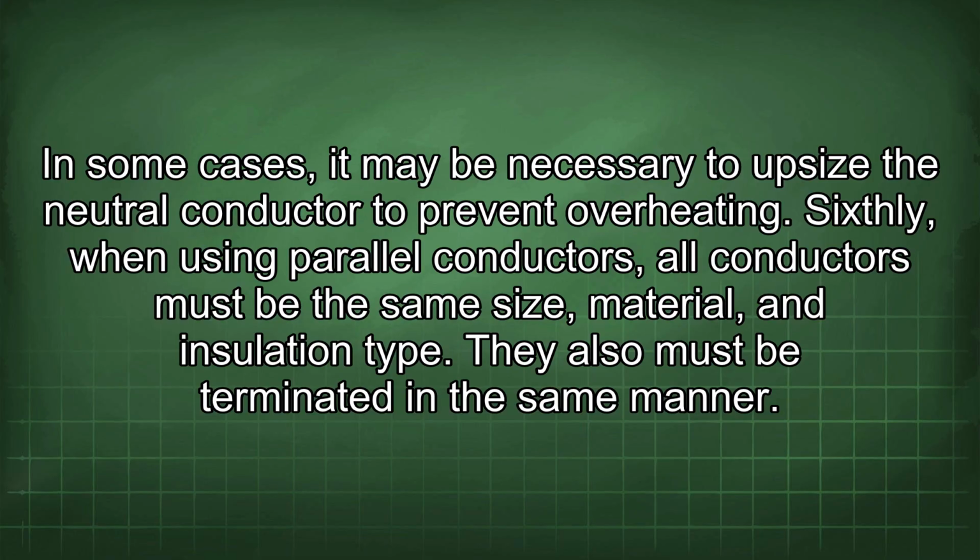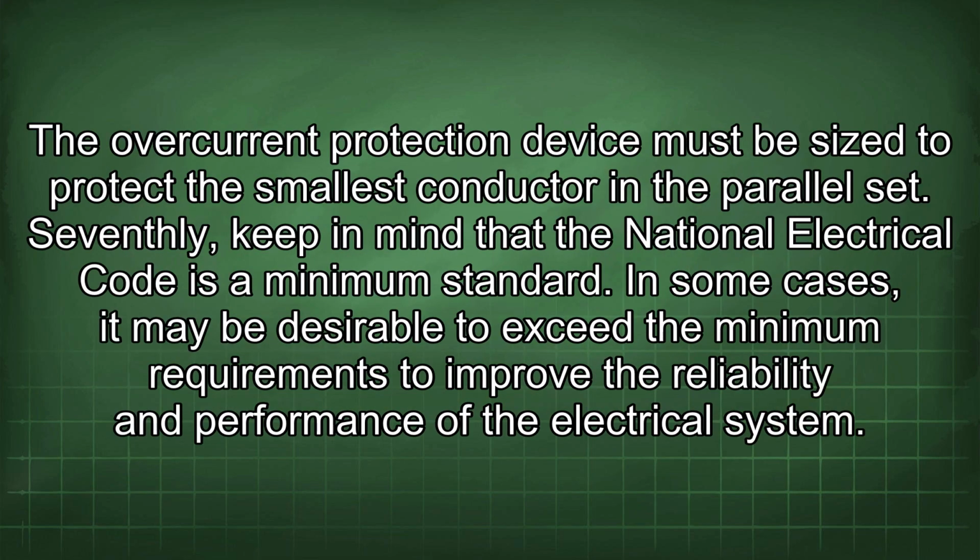Sixthly, when using parallel conductors, all conductors must be the same size, material, and insulation type. They also must be terminated in the same manner. The overcurrent protection device must be sized to protect the smallest conductor in the parallel set.